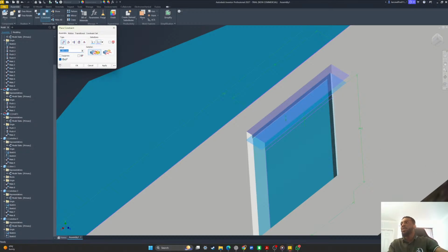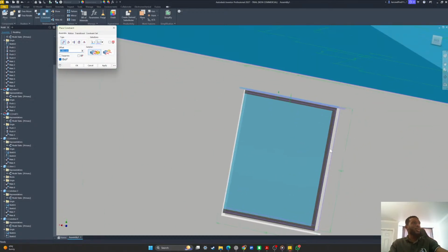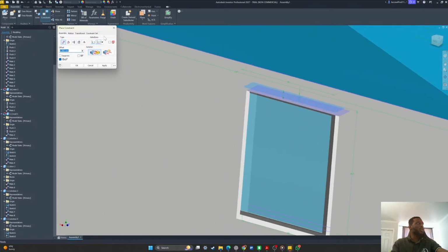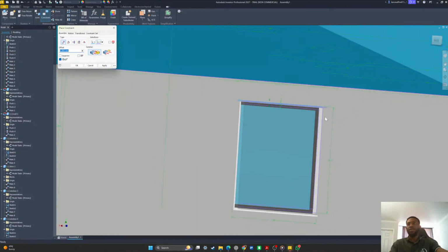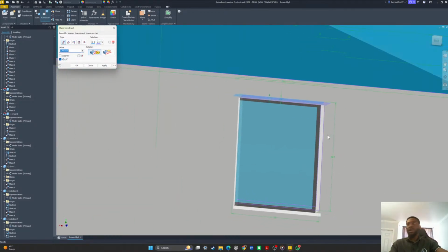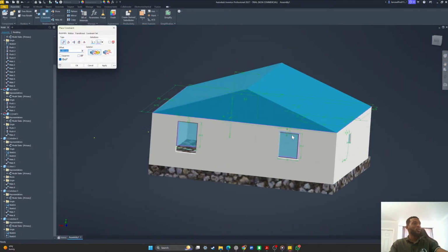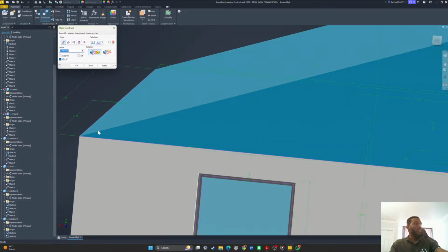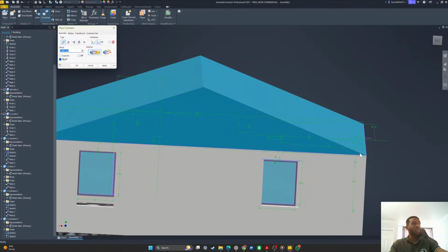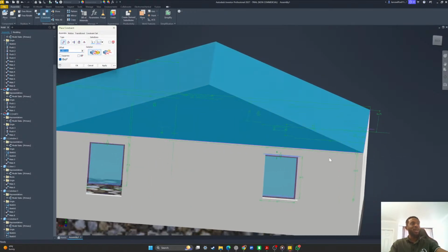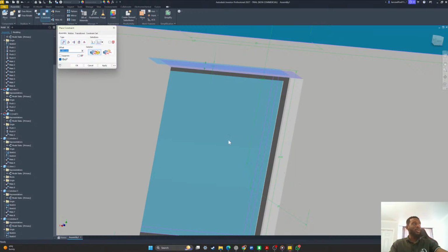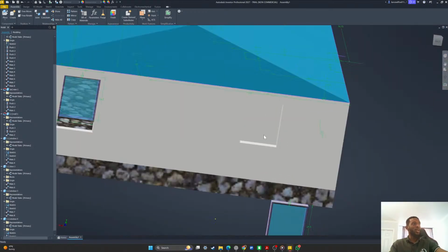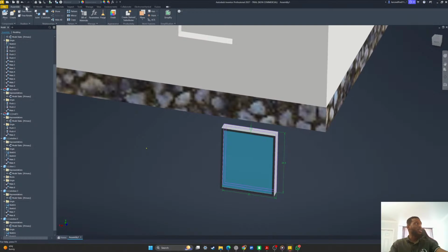Okay, so how do you make both sides of the roof symmetrical? A question on YouTube: how do you connect the house parts together? I have been using the constraint tool. It's a tool that lets you assemble the building parts together. If you check the roof dimension, I make sure that if the left was 25, the right was also 25. So that's how you get it to be symmetrical, ensuring that the dimensions are the same, basically.